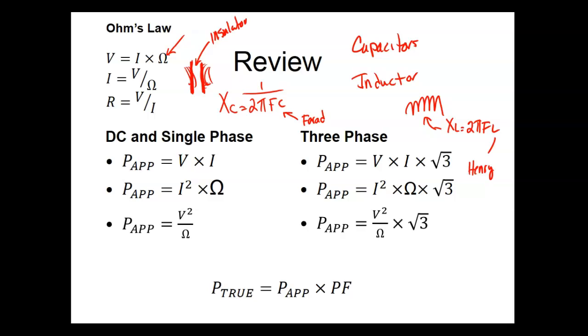And at a certain frequency, they cancel each other out, and that lets the radio station go, which is pretty good. So if your voltage and your current get out of phase with each other, it appears that you have more power in the circuit than you're actually getting work out of, and we call this apparent power. So we have what we call real power. So the power factor is equal to the work you're getting, or the real power, divided by the apparent power. So you pay for apparent power, but the work you're getting is real power.